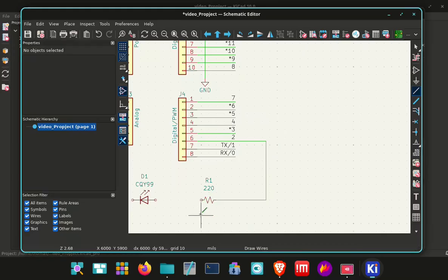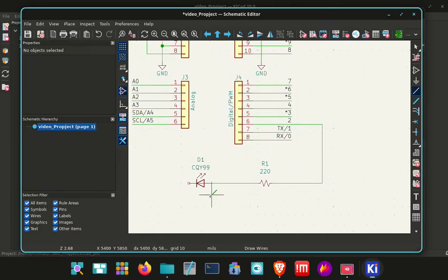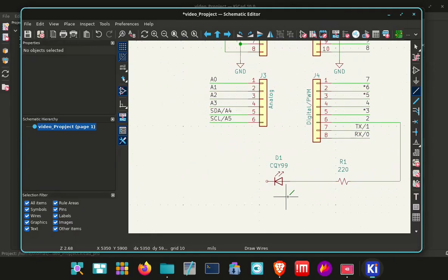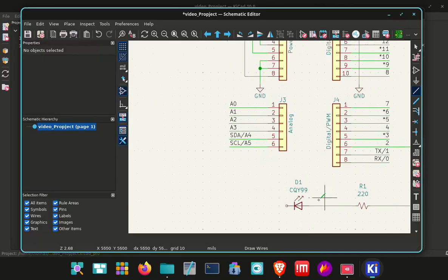Then we click on, if there's a circle like around here, there is no circuit made, so it's an open end. So we click on that one to there, and notice how the circles have disappeared. Now I use the middle mouse button push down to pan the screen across. We need to now go from the output of this resistor to the ground.